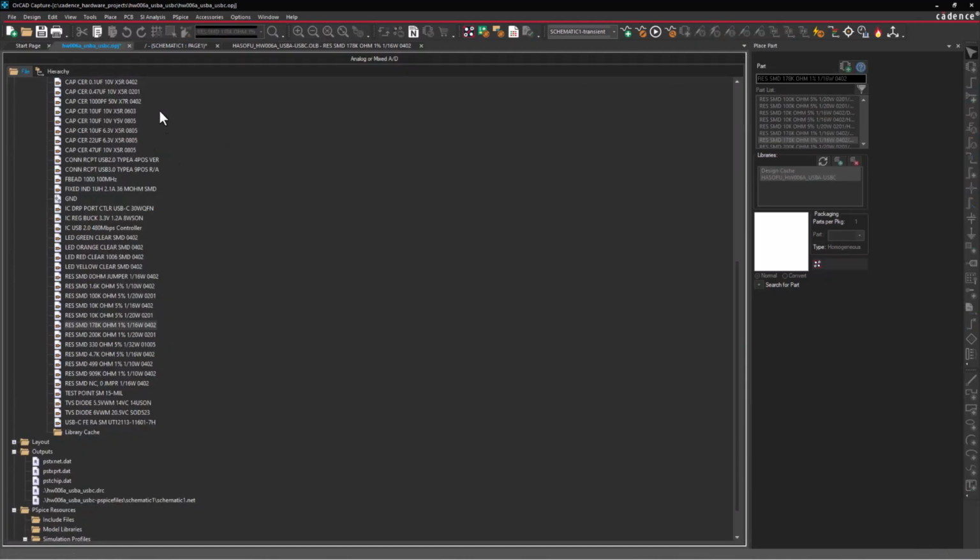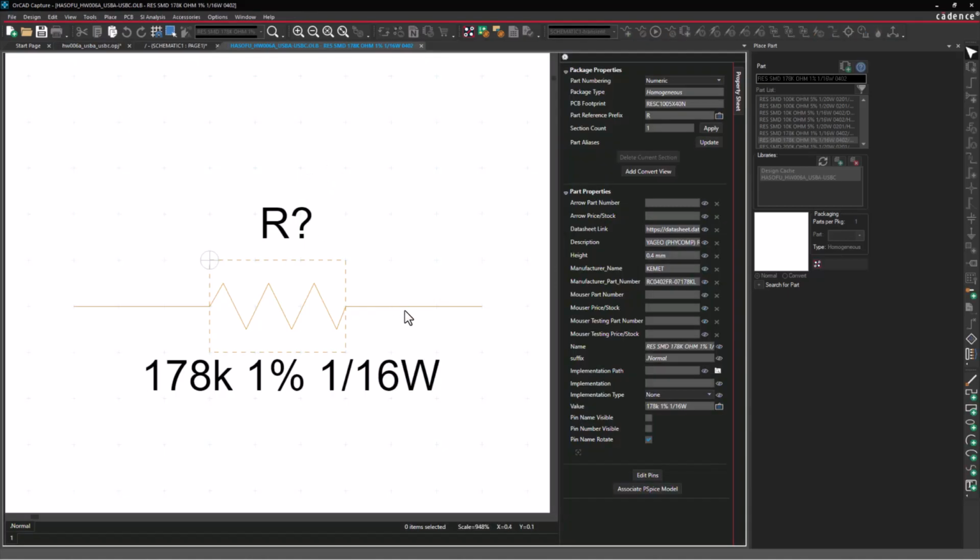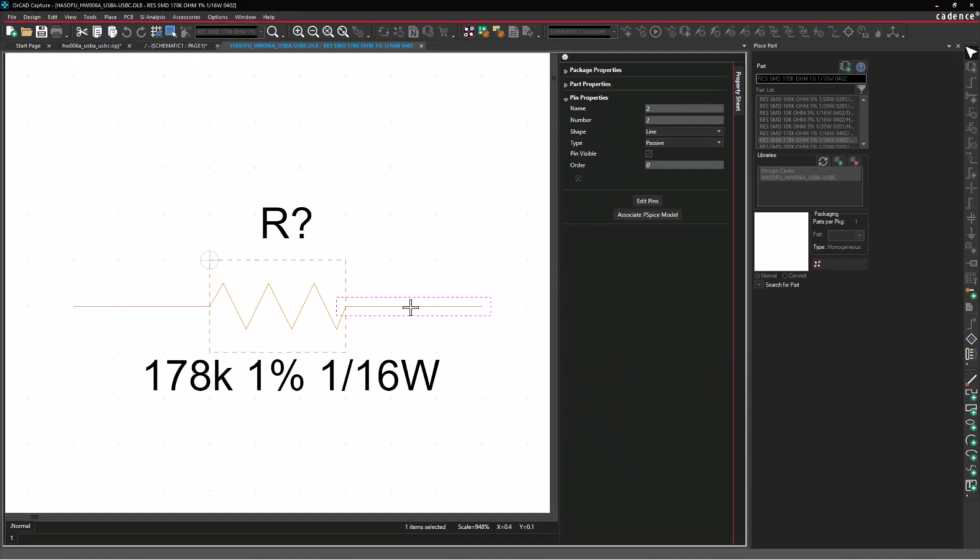It's better to just go into your library of components, into your .olb, or if you're using a different software, it would be in your library package, if it's in Altium or something like that, and then modify the part so that the pins end up on the dots of your grid, not off grid.